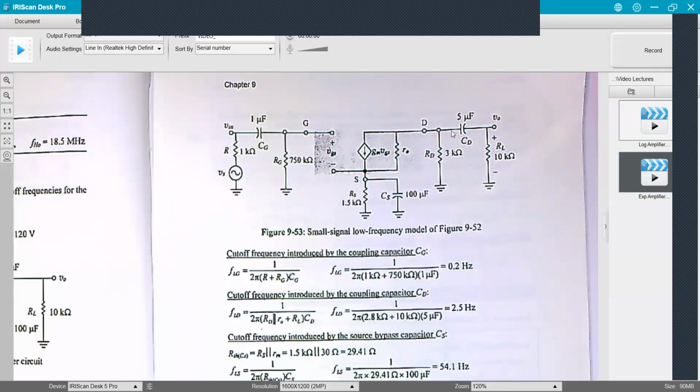Do you still want us to draw RO when we get on the test or homework? Yes. Draw it and do the calculations, and then on the exam, I'll tell you whether or not you can ignore it. But yes, you should. I want you to be aware that it's there, even if most of the time we decide we can neglect it. You don't want to pretend that it doesn't exist. It does exist, but we make the choice to ignore it because it's so much larger than the other resistors.